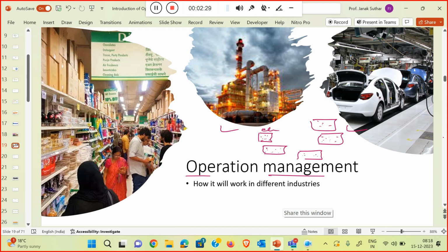So that is nothing but group technology, or you can say the cellular methodology. They try to make a small shop. If someone wants to take electrical-related stuff, he will visit this particular section, take all the electrical stuff and go out. If you put one electrical section here and another in another place, then unnecessary motion will be there. That reduces the efficiency of the organization, and that will not be appreciated. So layout design is very critical in the service industry. It is critical in the production, goods-based industry also.